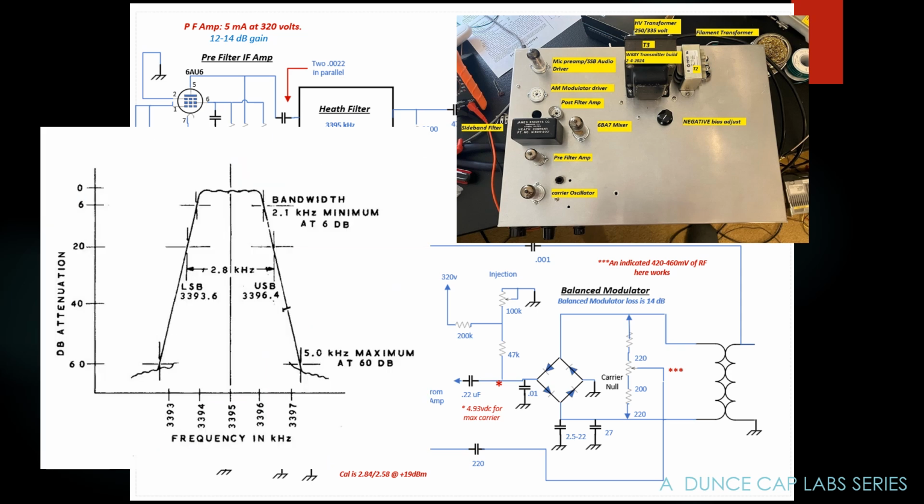This is the real frequency response of this filter. The reason I told you it was 3 megahertz, or specifically 3.0015 megahertz, is the math works out easier than if I had drug you through these awful numbers here. It just gets so confusing. So I moved the filter 394 kilohertz for the explanation. But other than that, everything I told you is accurate and the filter works as described.